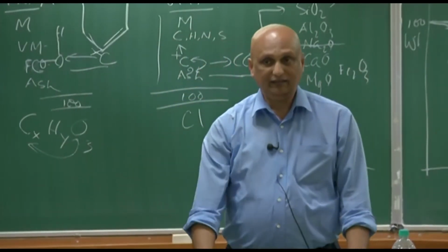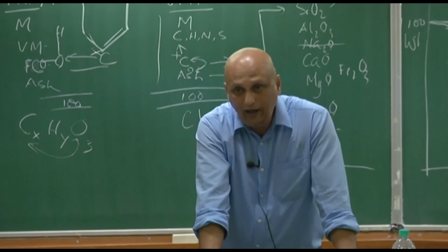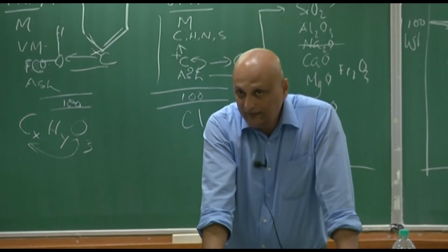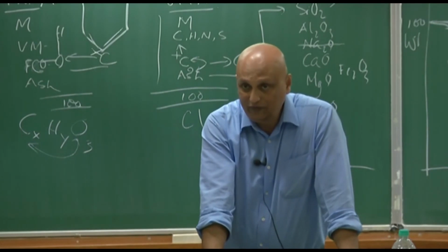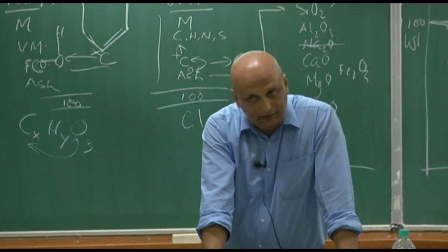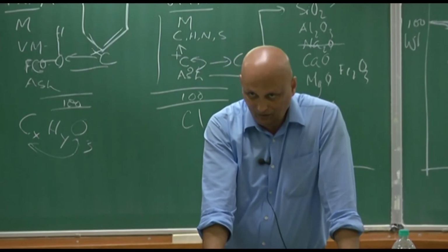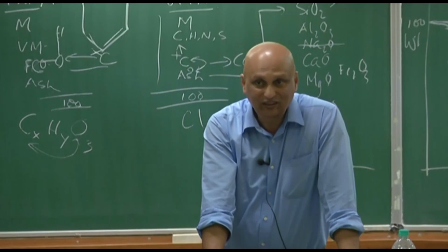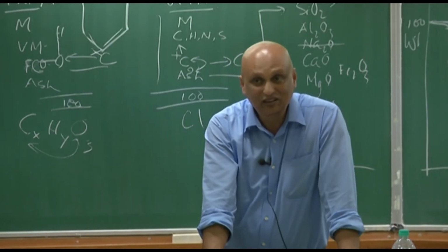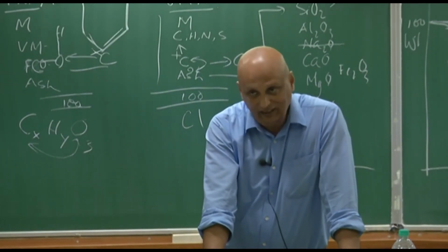Without digressing, the point I'm making is that if you have a molten layer of ash whose viscosity is low enough so that it falls away, then that's not a problem, because it will grow, but it will melt and it will fall. But if it doesn't fall because it is extremely viscous, then you've got the problem.